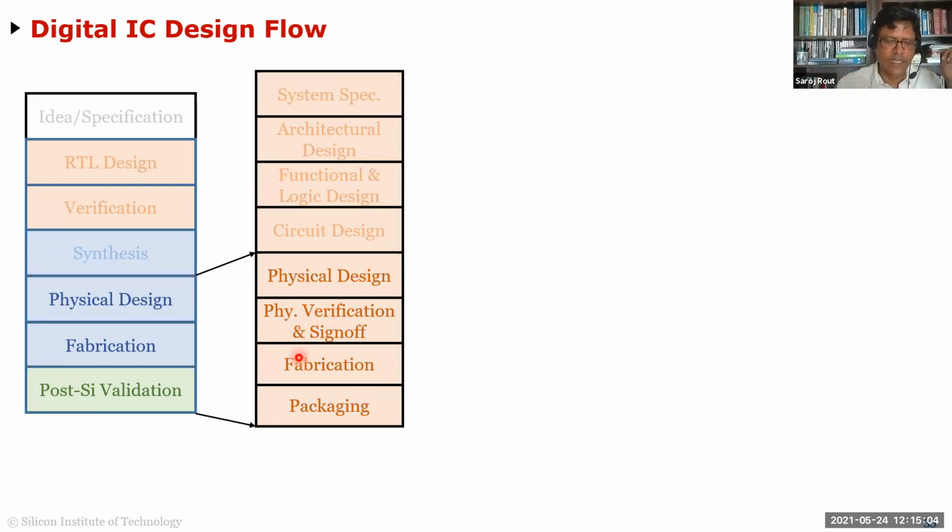Physical verification and sign off. In custom design, if I'm doing a small analog block, all this means is design rule check, which we call DRC, and LVS, layout versus schematic. Basically it means that whatever polygons I have drawn meet the design rules provided by the foundry.